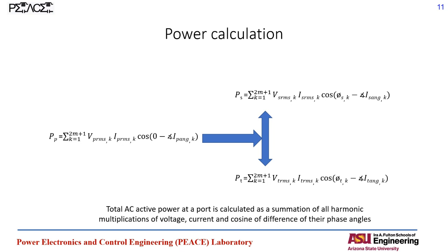Once we are able to obtain all of these equations, we can solve them analytically to obtain a particular value of the frequency and phase and deltas. By solving them analytically, for a given output voltage and output power, we get a distinct value of frequency and phases and deltas, which we can use to run our converter with.